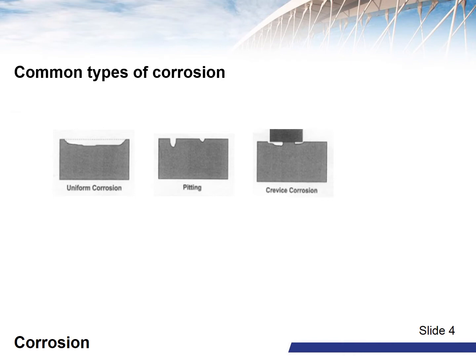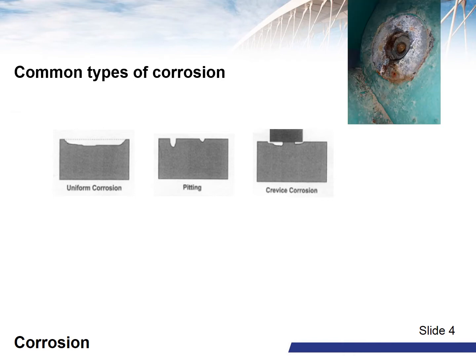Crevice corrosion. This form of corrosion occurs in areas where oxygen is restricted, such as underneath washers or bulkheads. This localized corrosion usually results from a difference in the ion concentration between two areas of metal. This stagnant microenvironment prevents circulation of oxygen, which stops repassivation and causes a buildup of stagnant solution, moving the pH balance away from neutral. This imbalance between the crevice and the rest of the material contributes to the high rates of corrosion. Crevice corrosion can take place at lower temperatures than pitting corrosion, but can be minimized by proper joint design.